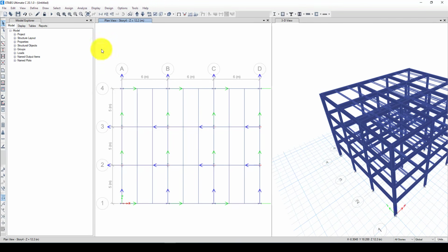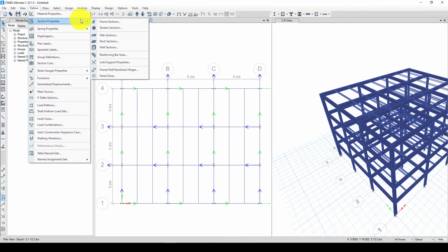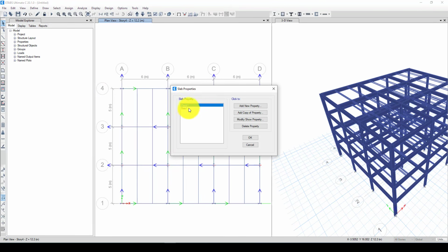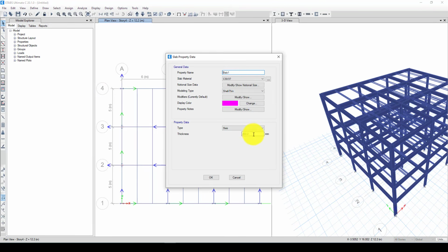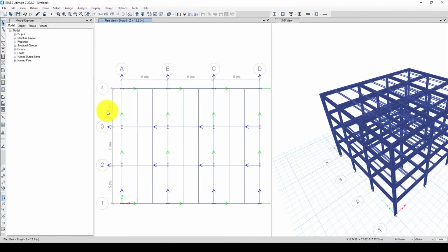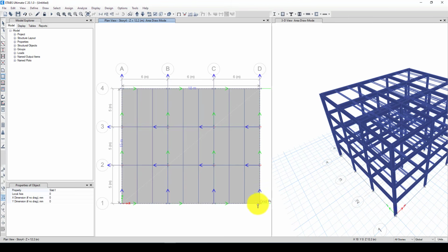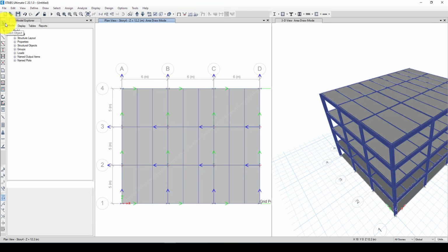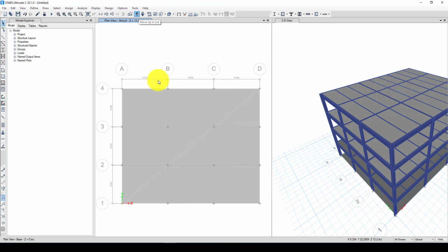The next I want to define a slab. Let me go to section, and it's called the slab section. So I want to use this slab. The thickness is about 200, so I'm going to give it 150. I'm using this concrete. Okay, and I want to select this one, draw rectangular floor, selecting this point and this point. And now the entire slab is added.